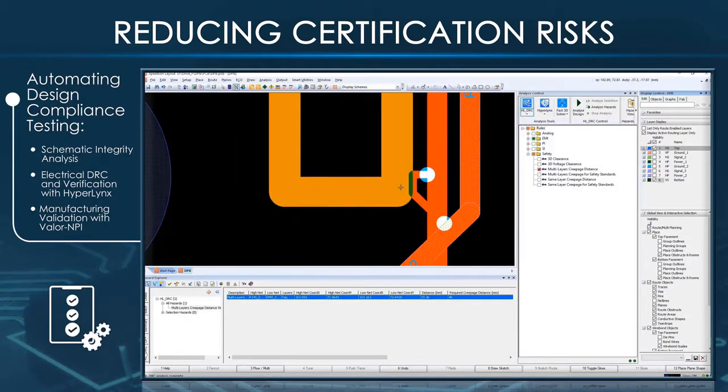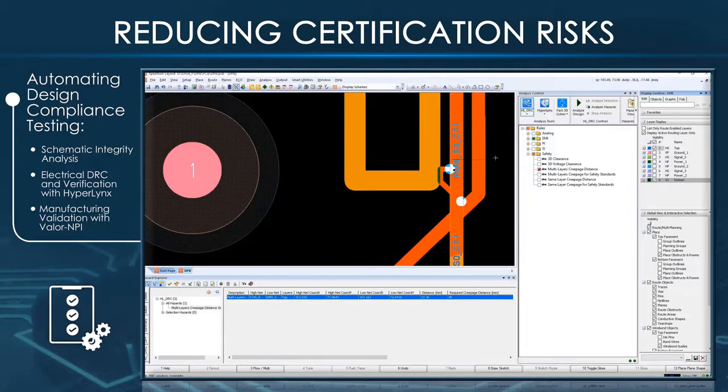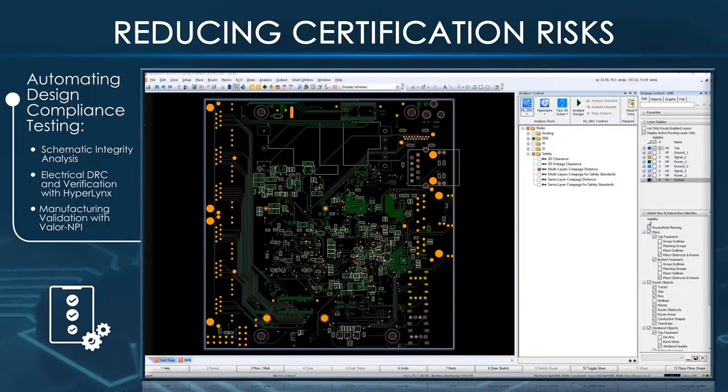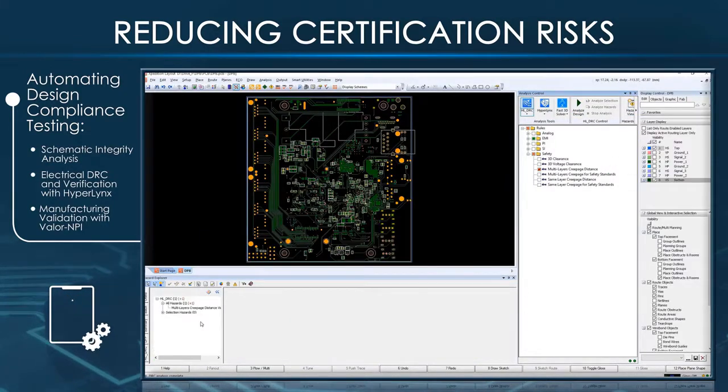And in this case, we have a high voltage 100-volt net aggressor on top side of the board. And you can see it's going through that slot in the board to the bottom side of the board and affecting an object on the bottom. So it's very tedious to check this way for the creepage as well in the high voltage.